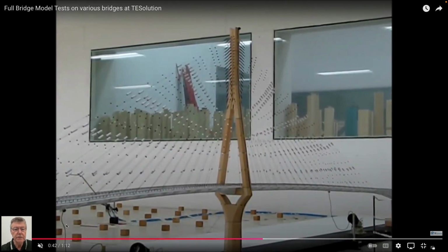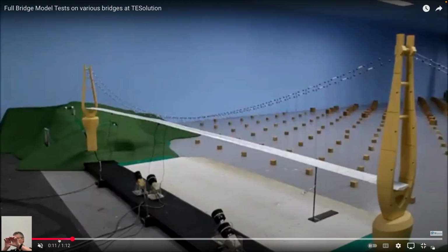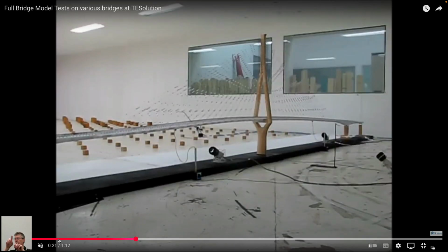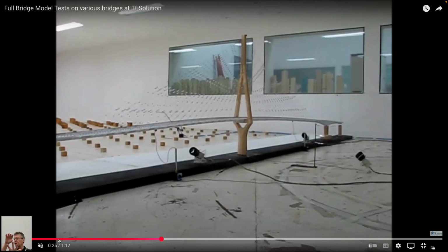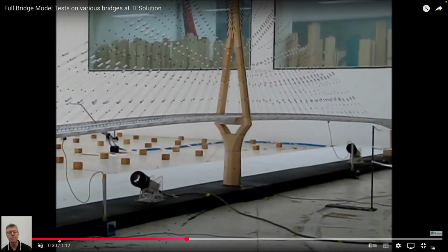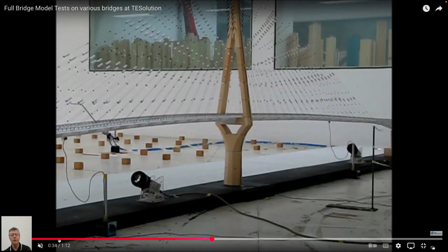And Tacoma Narrows, the whole problem is if you look at the section of the bridge, the cross section of the deck, which is usually a deck tapered at the bottom, if you have flow across that deck, and you see these little streamers showing that flow on the other side, as you get higher velocity flows, you shed a vortex from the top of the deck and then the underside of the bridge, and together it's like plucking a guitar string. And so that's what gives the bridge its motion. It's really just like a musical instrument.